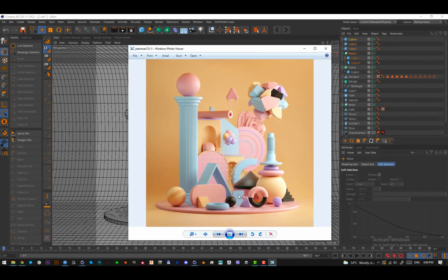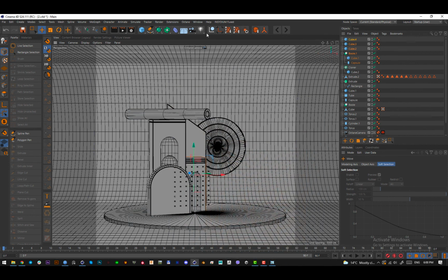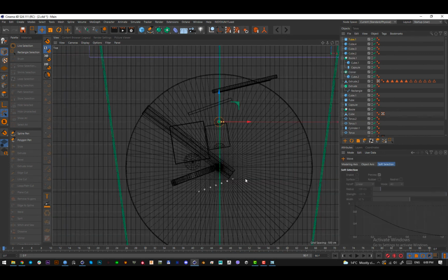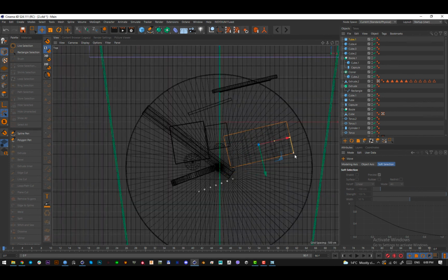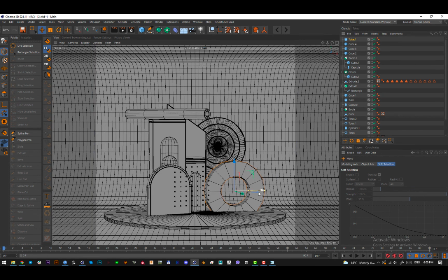Let's add this shape here. It's a tube, so put it somewhere here, rotate it like this by 90 degrees, scale it up, put it somewhere here, increase its width. Okay, jump in here. Let's add some rotation segments so that it's smooth.